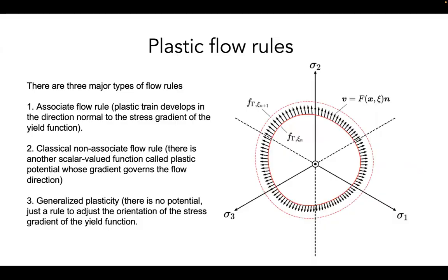So what is the plastic flow rule? The plastic flow rule is like what I'm talking about. It governs what type of plastic strain I get. For J2 plasticity, I get a circle, and if I use something called the associative flow rule, the normals to the yield surface are all pointing outward. If we look at the cylindrical object, what I find is that I'm going to point it all out on that principal stress space. I won't point it in here.